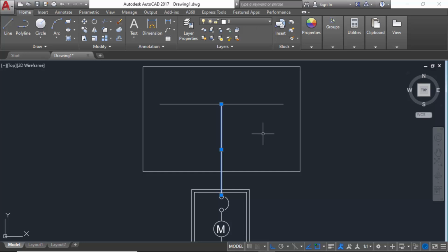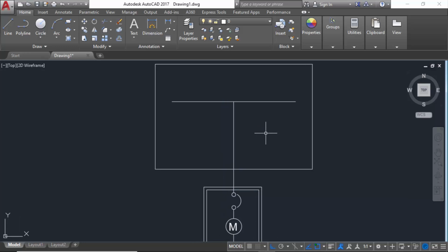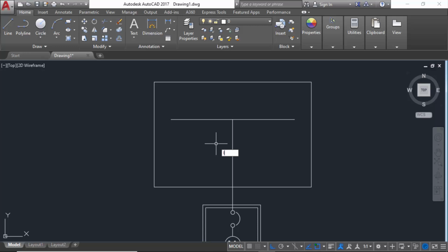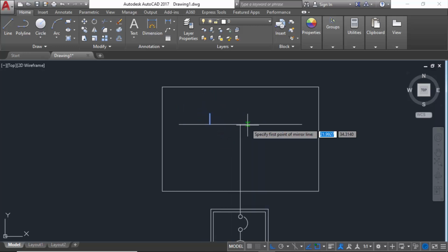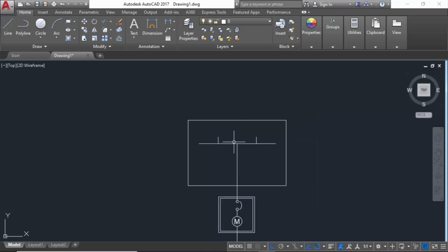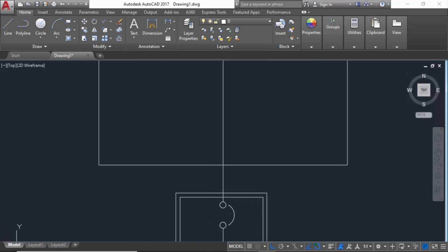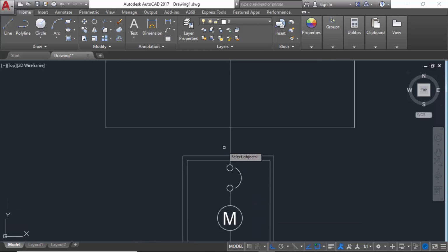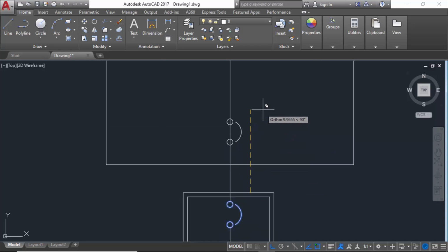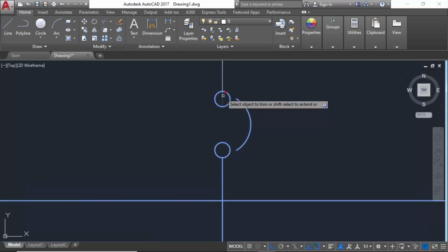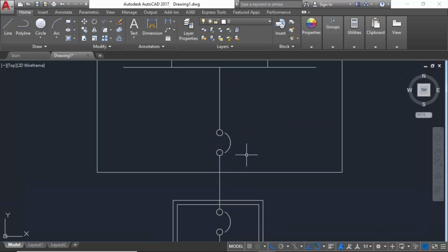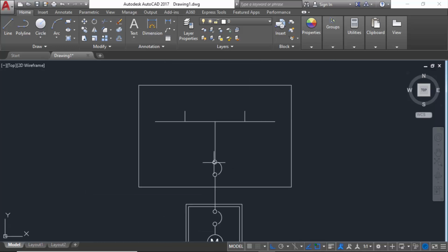This one is the ground floor, and now as you can see, here also we have to create another MCCB, because we are giving the connection to our house, and each MCCB will serve each floor. So now here also we have to put the MCCB symbol. It's the very first connection prior to the bus bars.